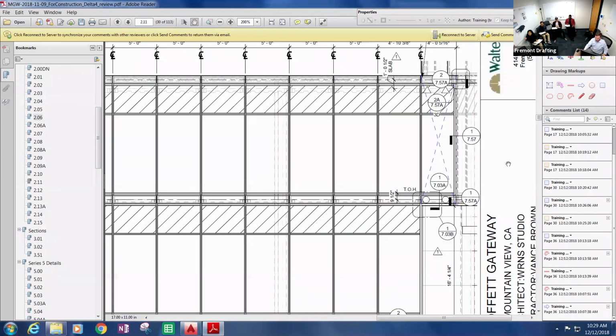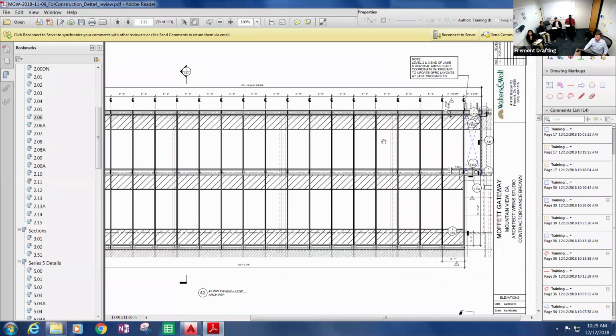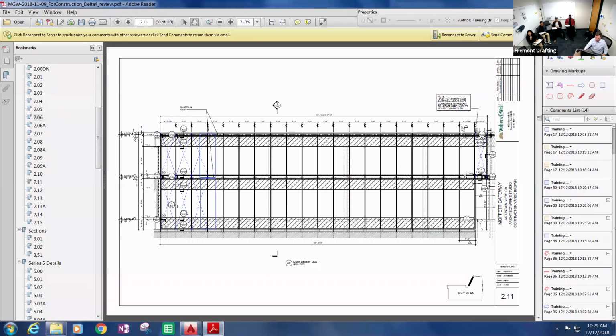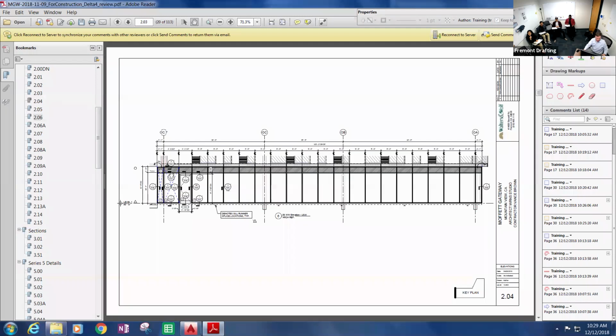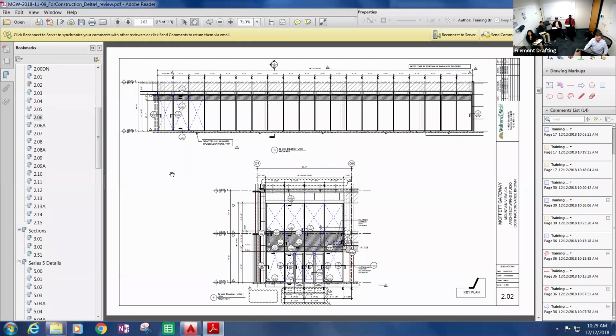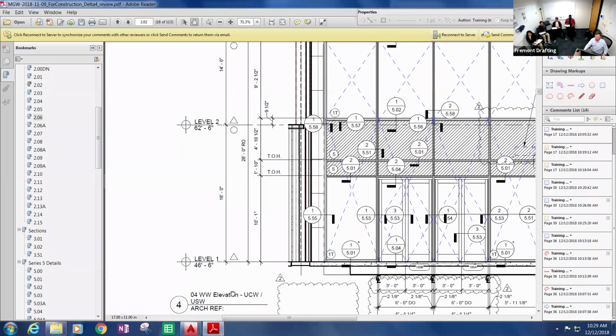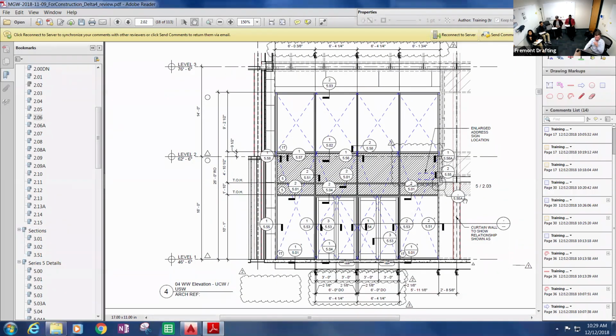Oh, no, but see how here, you can see they've added some symbols where it changed. But again, that dead load's up there the whole way anyhow. Because it was different, they wanted to make it clear, so they added them in just there. Maybe that other step one might. Maybe not. But normally, if this had been a big full elevation and then all of a sudden it had some doors over here by the dimensions, it would have had a wind load connection, dead load, wind load down here, and then over here we would have put in dead load, wind load to indicate specifically.